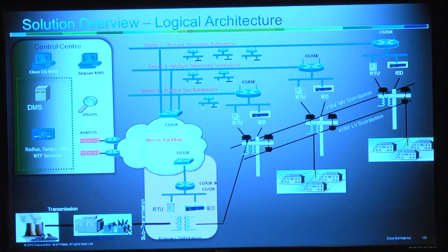So you had sectors being created upon which individual substations could then be joined onto the same IP segment. Effectively, that allowed all those various RTUs, IEDs, and various other devices to be interconnected over the one IP-based network infrastructure. You can see there how everything was then interconnected together as a representative model.